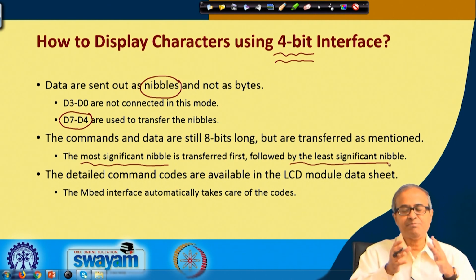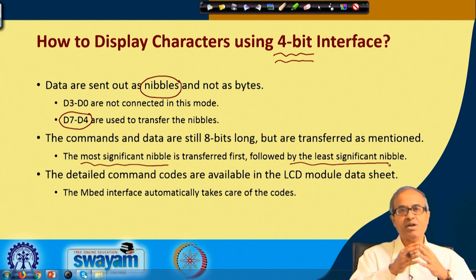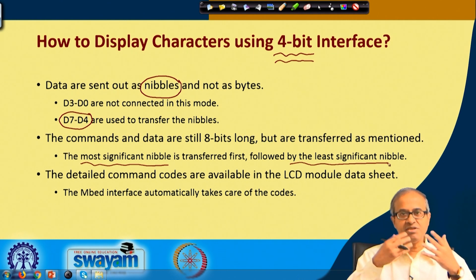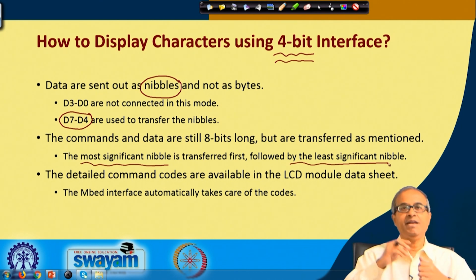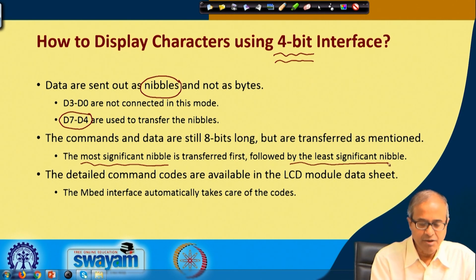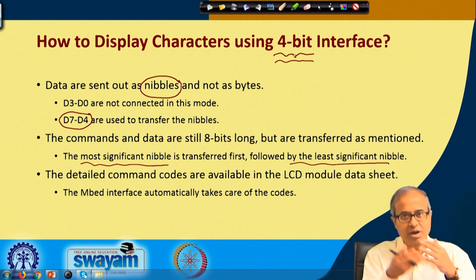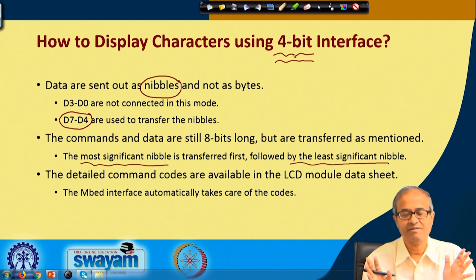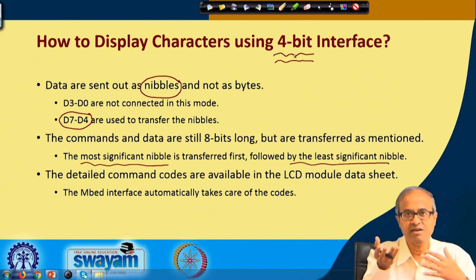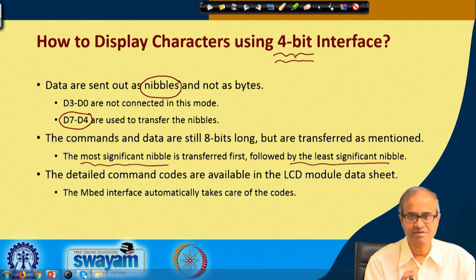Now, for these display units, the way we shall be showing the demonstrations, for example, with the STM32 board, we will be using a programming environment called Mbed. This Mbed programming environment allows us to develop our application in C and it provides a host of library functions and drivers which we can use. In the library function that we will be using, this 4-bit interfacing will be taken care of automatically, and while writing the program we need not worry about anything. The driver will automatically take care of writing the high order 4 bits first, low order 4 bits next, and so on, and when to write instruction and when to write data.